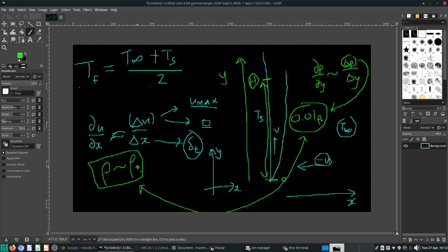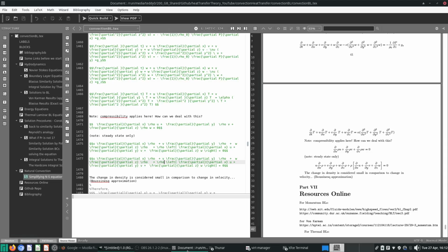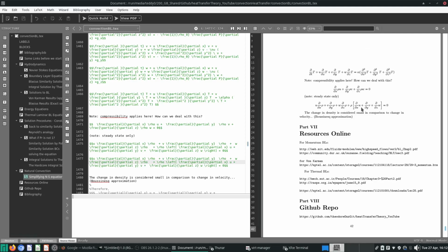I'm not going to do all the non-dimensionalization for you now. I'm just hoping to say that we can actually ignore all these terms, even though the fluid is technically slightly compressible. Because these terms are so small compared to the rho over here, we can just neglect them, maybe 100 times smaller in fact. Both these terms are small, but these terms here are smaller than these terms here. That's the point I'm trying to bring across. Hopefully that convinces you. Of course, you will have v del rho del y, and let me slow down and pause a while. Maybe I'm going too fast.